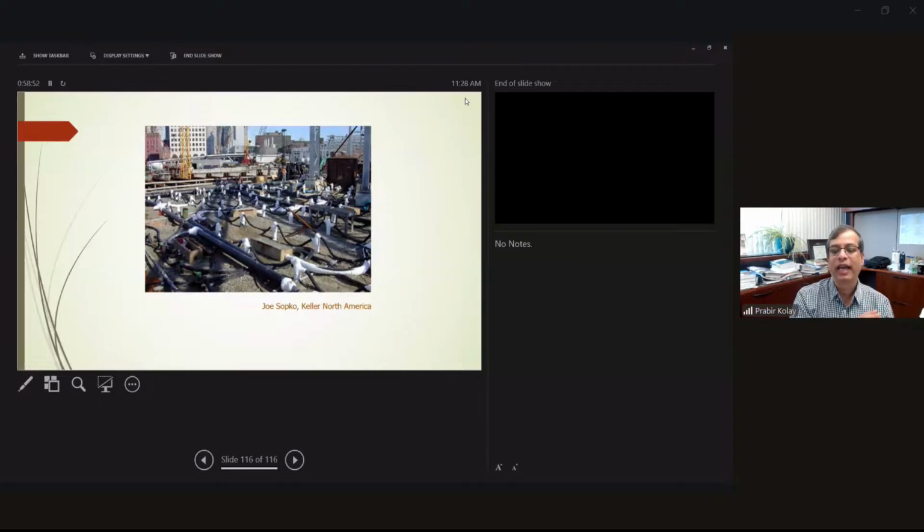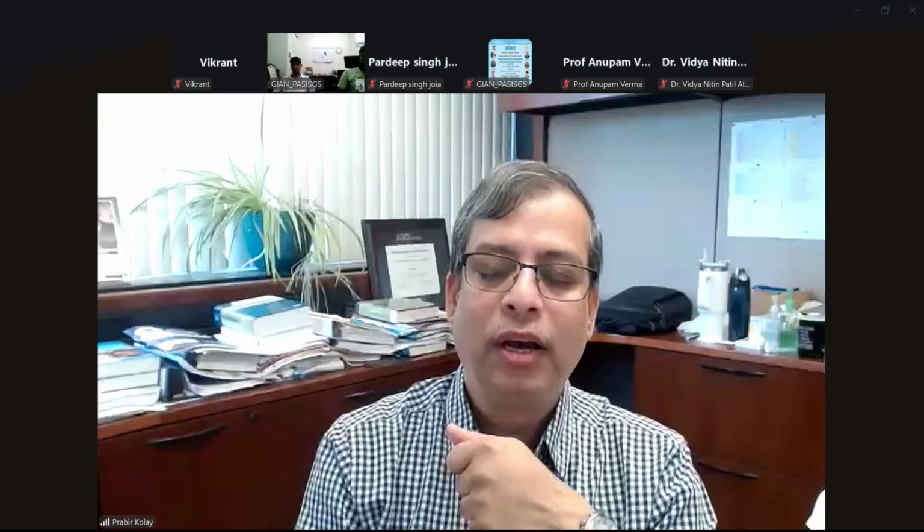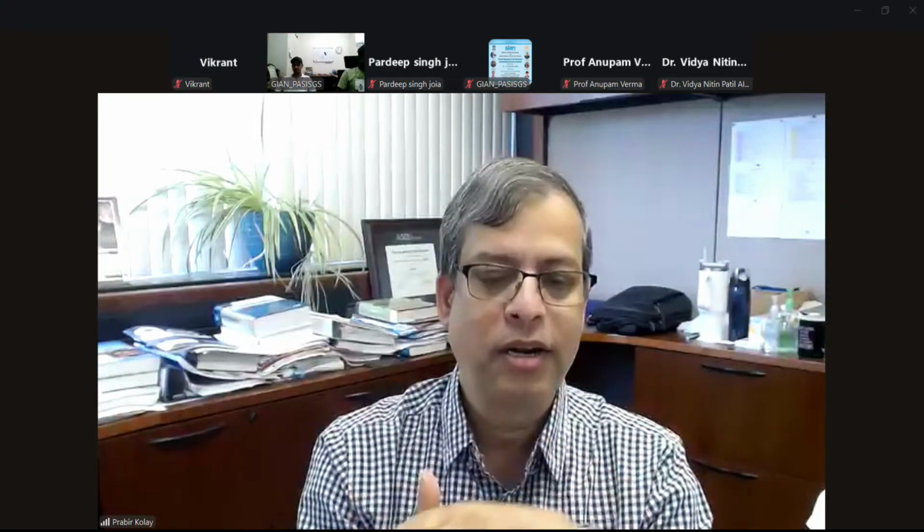Okay, so I think that's all for this ground freezing. I just went over it quickly for the sake of time. The ground freezing tool, as I mentioned, go to the ASCE site, Geo-Institute, Geotech tool. This is the one we developed last year, with all these techniques. Specifically, Joe Sopko is the expert in ground freezing. There are a lot of projects in California and New York where they use this ground freezing technique, especially for tunnels and drilled shaft foundations.